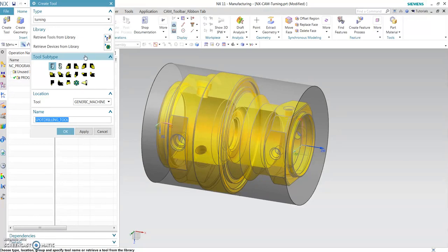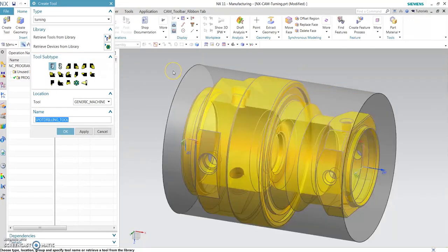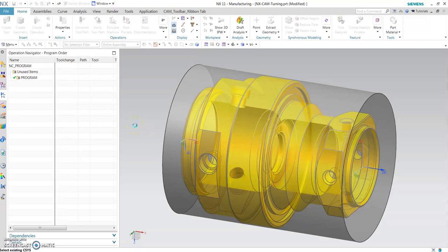It's better to select an 80-degree diamond insert. That's going to be a CNMG. I will cover all that alphabets, what it means for each alphabet, what it means for the tool, how to select the shank size. So right now we'll go back and select the CNMG insert. Okay, it's an 80-degree OD cutting, left hand insert. Select OK. Take from the library.